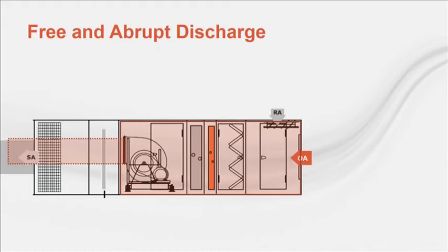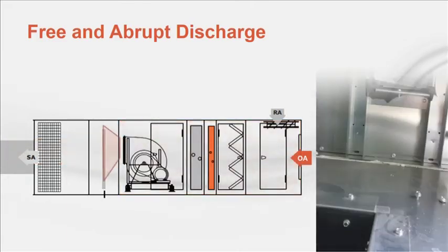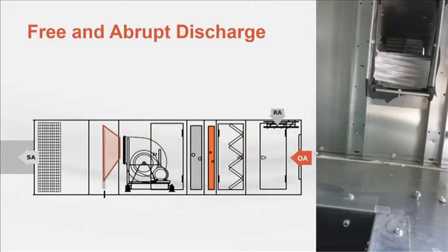A fan is designed for and tested with a duct connection that's about the same size as the fan discharge. If the duct isn't present, the fan performance will deviate significantly from the AMCA 210 test. Any pressure measurement taken downstream of the fan won't include this effect. This loss can be significant, as high as 1 inch in some cases.